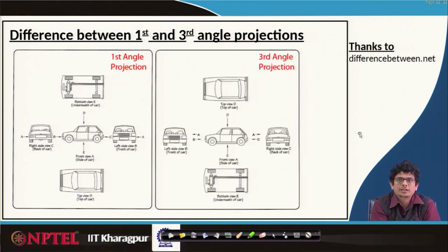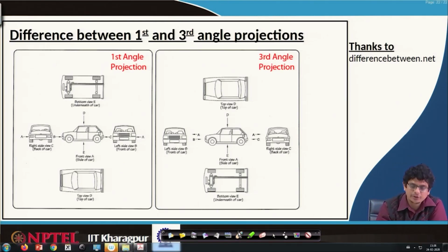Let us look at how third angle projection is different from first angle projection. In third angle projection, the object is supposed to be in the third quadrant, and the third quadrant is bounded by transparent walls. We have to project this entire object onto those walls, opaque and transparent walls, flip and rotate these at suitable locations, like folding and unfolding, and then we will have the complete picture of third angle projection. Let us carefully look at it.